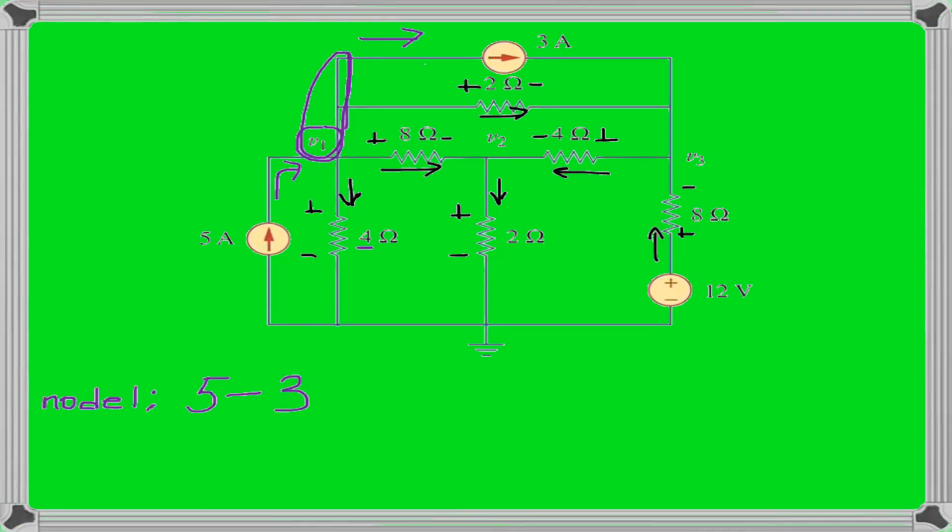The next current is 4 amps. The current is going down, away from the node, so again it's going to be a minus. And let's write the value of the current. The current is expressed via voltages using Ohm's law, voltage over resistance. Talking about voltage, we take the voltage at high potential minus the voltage at low potential, divided by resistance.